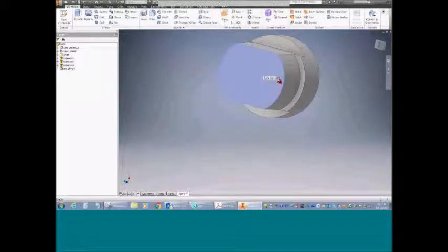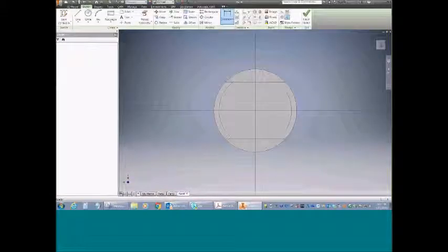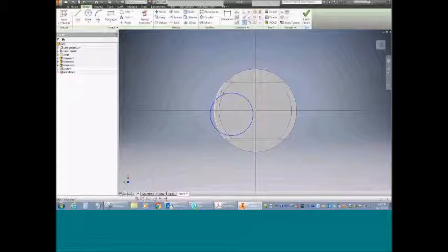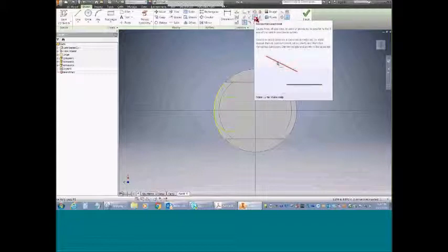So create a new sketch on this, and have another cylinder coming off of this, and it is not concentric. So for this one, what I'd ask them to do is use the tangent constraint, or I'd show them that I can make that tangent to that circle, and then I'm going to use my horizontal constraint.